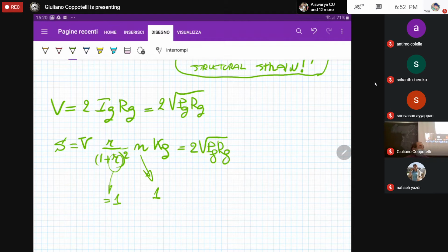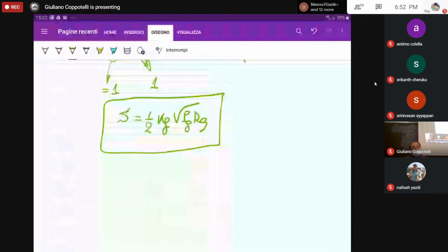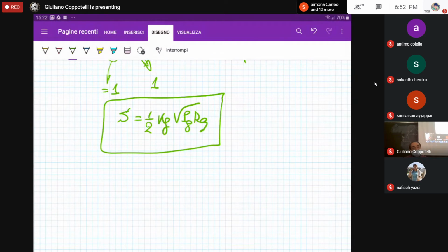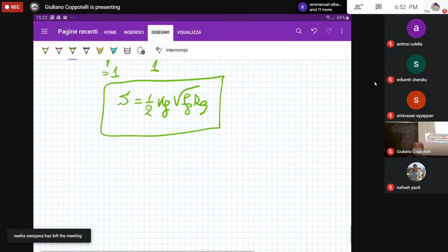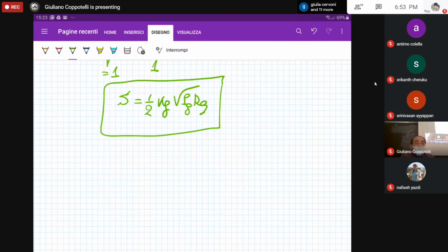To this must be subtracted the change of resistance of strain gauge number 2 that is feeling just the temperature. Thus, it is compensating what is feeling strain gauge number 1. So at the very end, the overall change of the resistance is just taking into account the physical strain, the structural strain, because the temperature induced strain is compensated with this configuration. The resulting sensitivity is there.